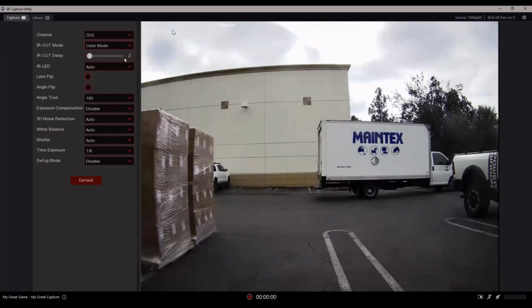Or a lot of times when you're using a dome camera and you adjust the dome inside, the IR is being blocked. So the camera thinks it's either daytime or nighttime. It's not getting enough. You want to make sure that the IR is able to see light or not see light. So a lot of times that's the situation that happens.